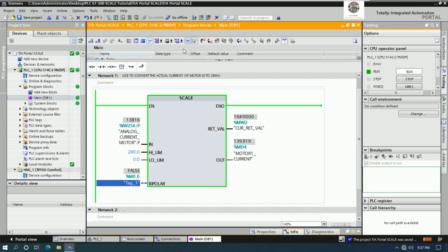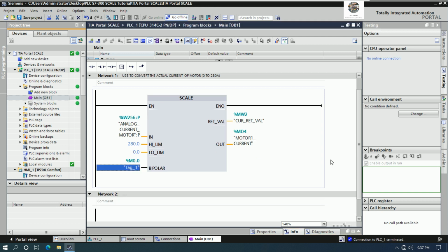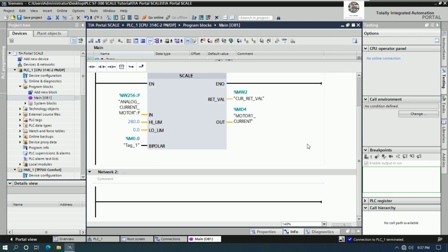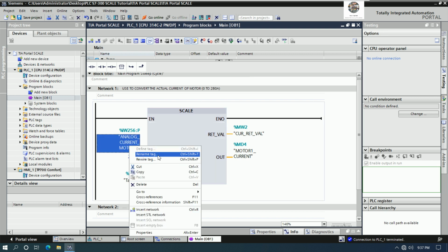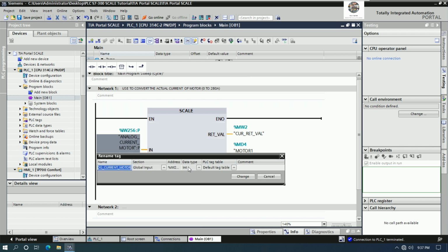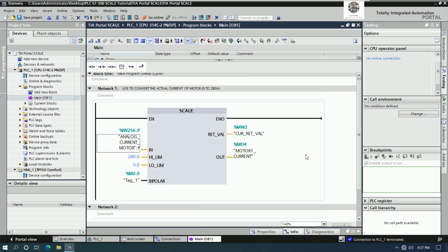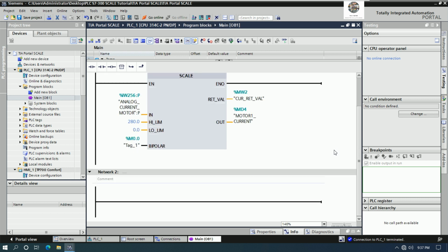Okay, I will go offline first. And for the analog signal with the PT100, we cannot use the scale formula. Yes. So we need to convert from the raw value, convert from integer. Actually this one is integer. Let's see here, the data type is integer, so we need to convert to real, right?